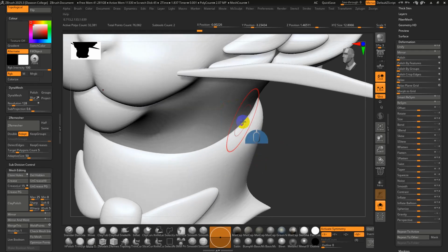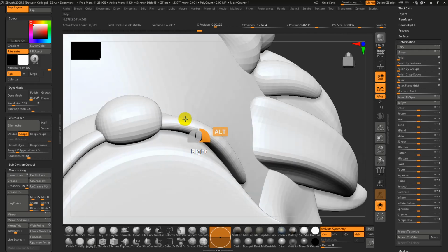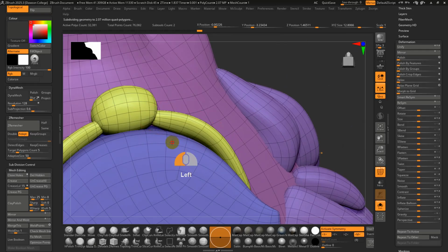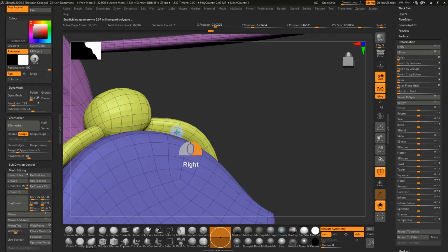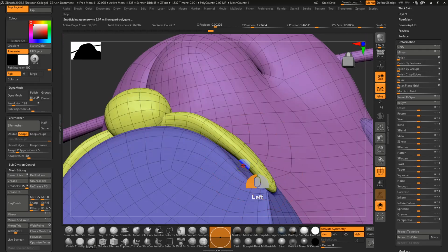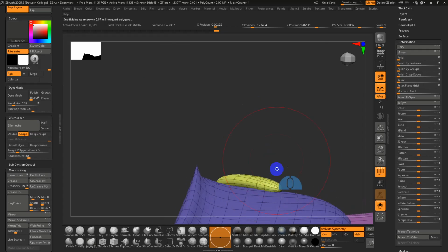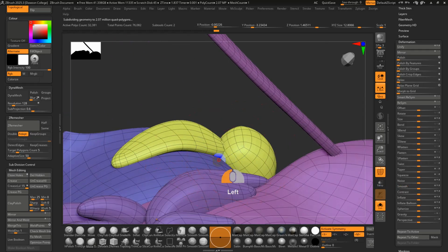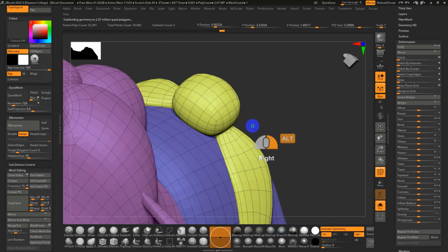And again, if there's ever any opening between, let's say, the neck and the collar, I would want to get rid of that. So this stuff here, for sure, I'm going to just pull the backside down so it's not going to have that gap or that cavity. That helps quite a bit. And check from the top side, because again, we want to avoid voids if possible.